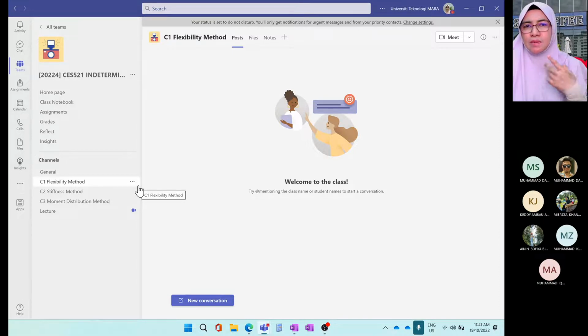So analysis of determinate structure including calculating reaction in beam, frame, truss, and then writing moment equation in beam and frame, and determining member forces in determinate truss, and after that, from internal forces, how we transform from internal forces to calculate displacement.